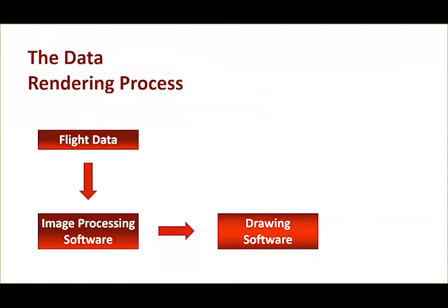So they're utilizing a file format, either LAS or LAZ, that brings in the XYZ data along with the RGB, otherwise the real-time color coding of those data points, to allow you to bring them into these programs and conduct a virtual survey. You're able to establish a coordinate system and then select points.